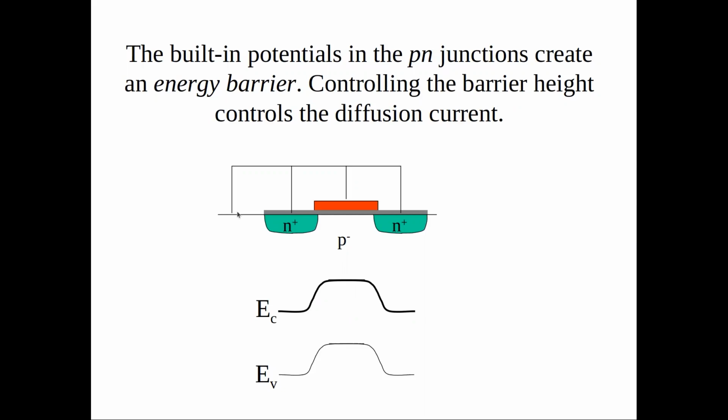The source, the gate, and the drain are all connected together, and to the substrate, to the reference voltage. There you see an energy barrier between the source and the drain. It's not allowing charge to flow from left to right or right to left. In order to have current, you would need to overcome this energy barrier. So you can think of it like that.